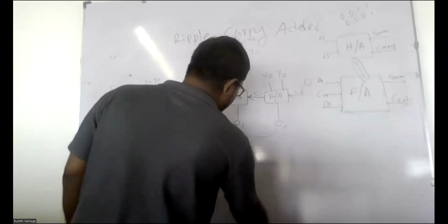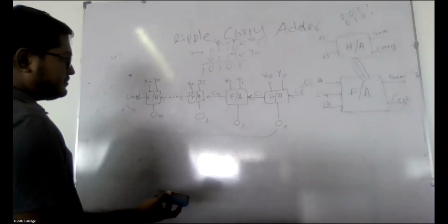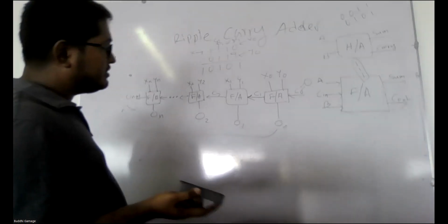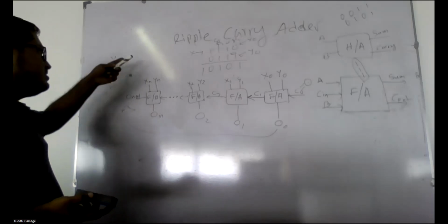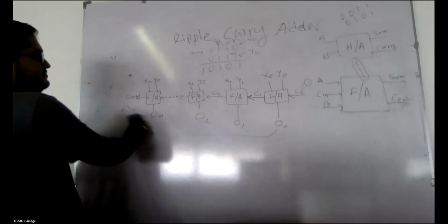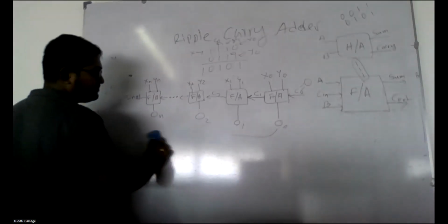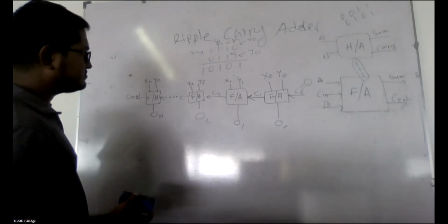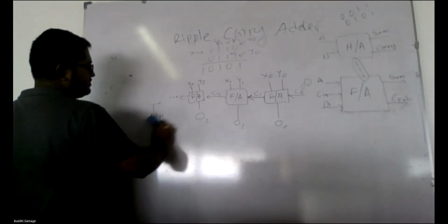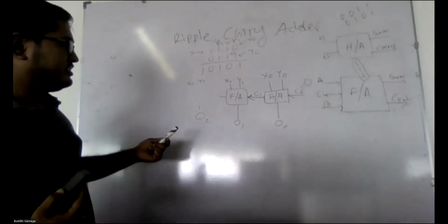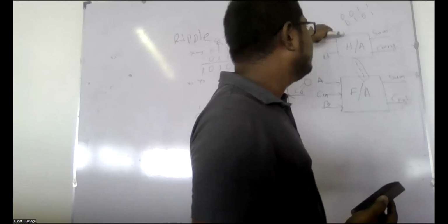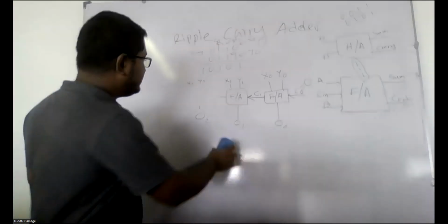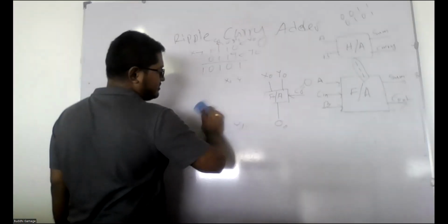And I have explained about the half subtractor. So you can design the full subtractor, and you can even further extend it to something like a ripple carry subtractor to subtract any number by using logic gates. The method is simple. You first identify the concept, draw the truth table, identify the gates inside, and then design the whole circuit.